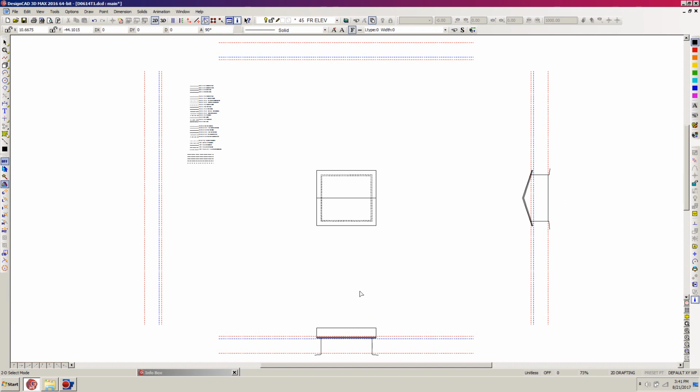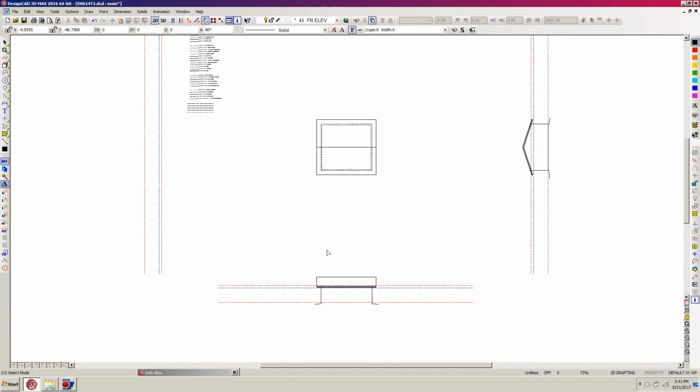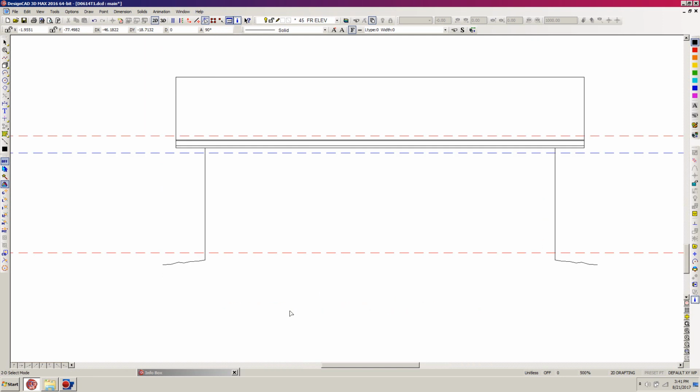Lesson 10B is going to be really pretty quick and dirty because I forgot to do my floor line. So hit Z to zoom back up here. I'm going to just hit I want it to be right on this line right here. Even though the floor at the garage door is going to be lower because it's sloping, I'm just going to use this intersection of our typical finished floor line and wall line.